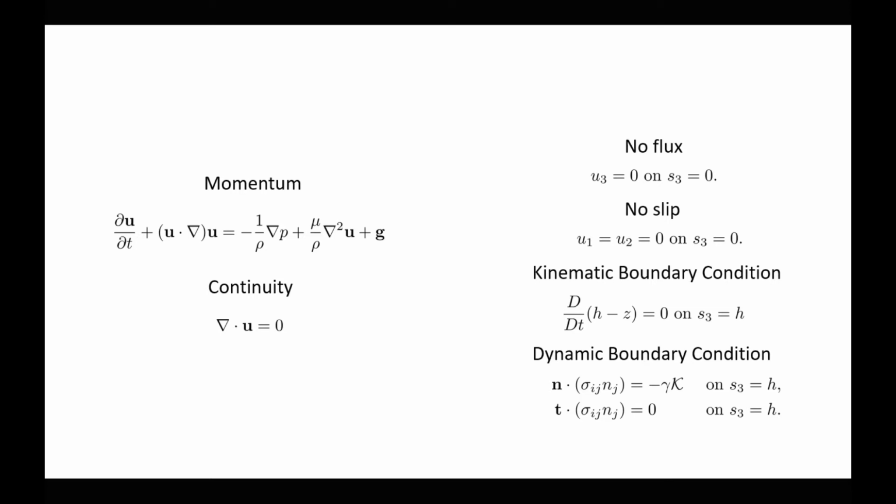The normal component gives that pressure jump across the interface is balanced by surface tension. Meanwhile, the tangential component gives the jump in shear stresses across the surface, which for the duration of this reading course we neglect. In this final equation, the letter K denotes the free surface curvature. We observe that the first 2 terms are related to the substrate's curvature, whereas the third term corresponds to the film itself.